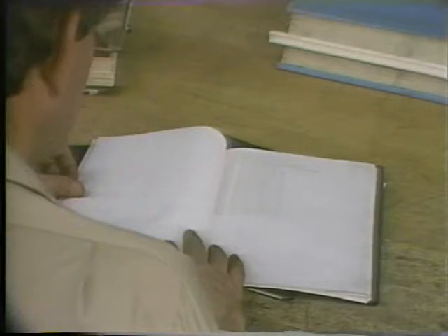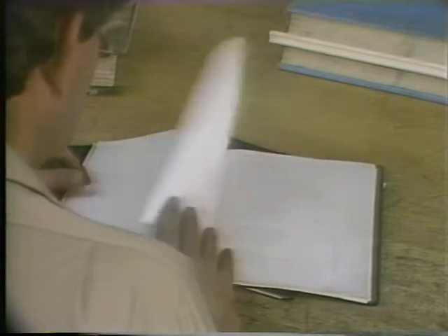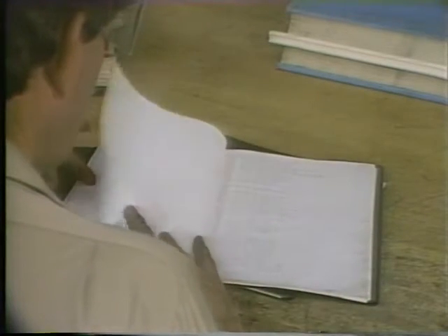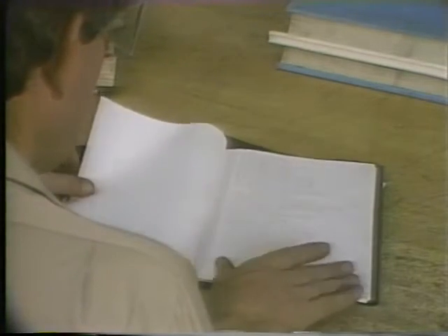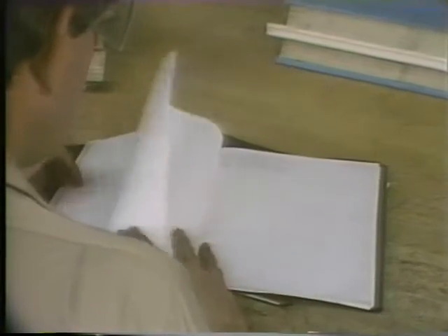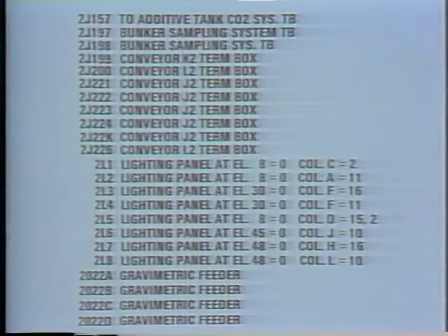It uses standard number-letter abbreviations to identify equipment rather than the proper equipment names. Most modern plants use the standard letter-number combinations. Now, the equipment location index is usually rather long, so we're going to look at a few specific items. We'll show you an example of how the list could appear, and we'll point out some features that are common to the lists. This particular plant's equipment location index is made up for equipment that is part of 2 generating systems. In this illustration labeled 2L1, the first number designates the system.